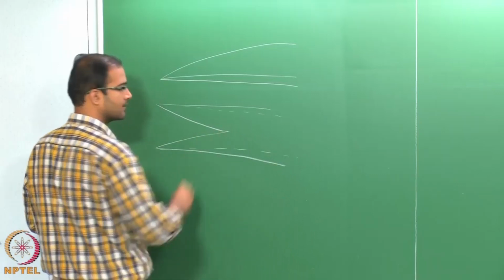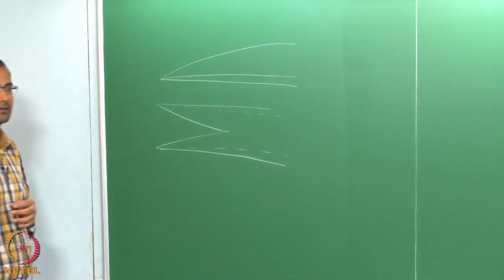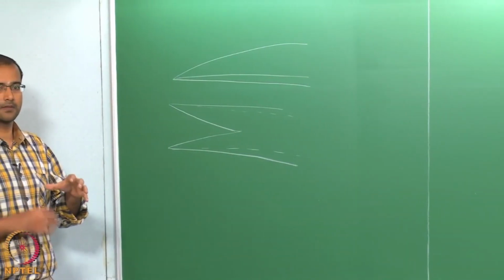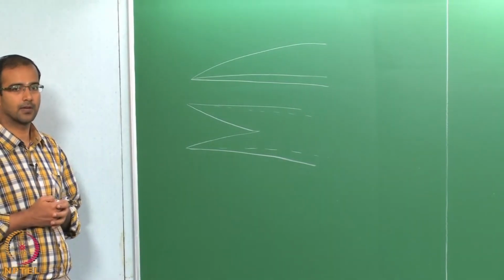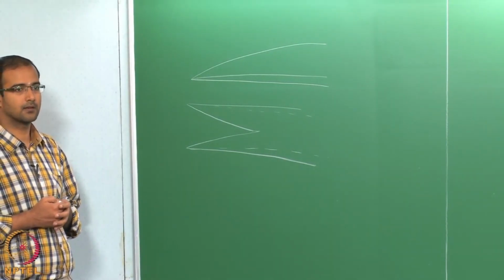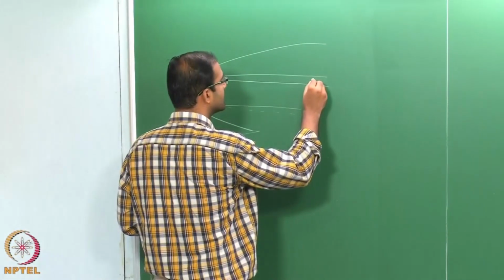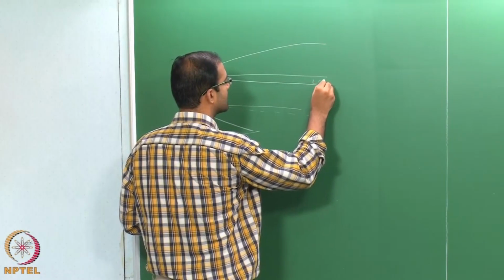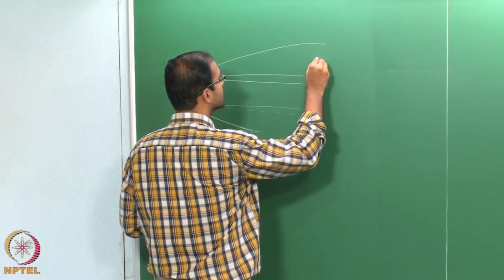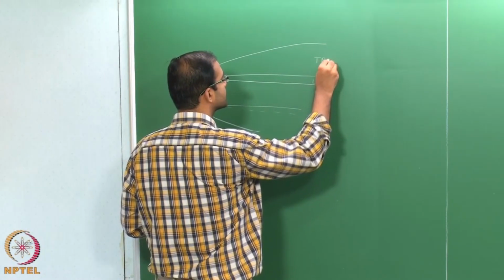The turbulent boundary layers merge, but there is a small viscous sublayer which is actually still growing in the case of turbulent fully developed internal flows. So in these cases you classify this as a laminar sublayer and this as your fully turbulent boundary layer.